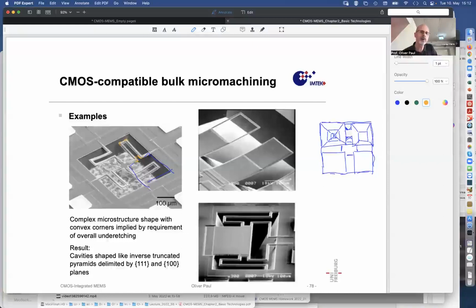So what could look like a single cavity here is expanded at that corner towards the cavity that could be considered a single cavity here. So those form a big cavity together. And the cavity that is formed here is under etched to join the other cavity. And then after some while, everything becomes one big cavity. And that is exactly the point. You have to allow the etchant somehow to be on the edge.